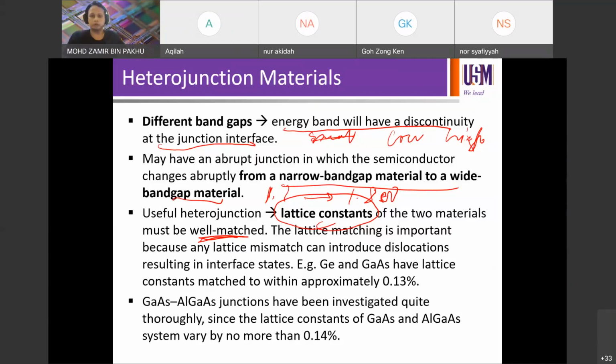If you combine two different materials, then you're going to have some mismatch due to the different lattice constants. Not yet, right? But you learned about lattice constant, and this is applying the lattice constant to a real device. Before, in 307, the lattice constant of this material is this, and this one is this. But now you're combining them to see what's going on in the real device.